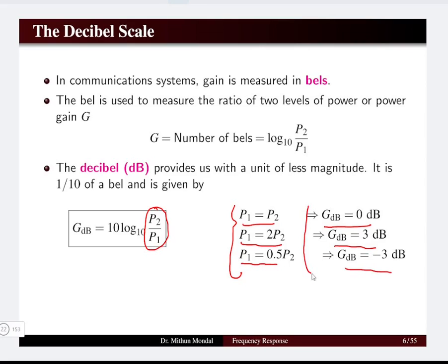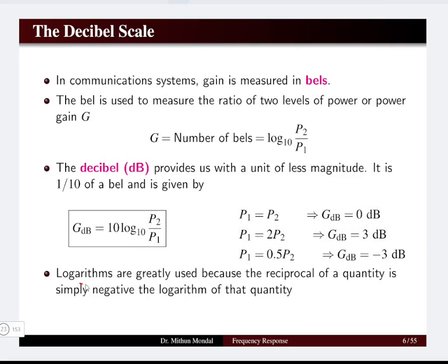So these values will be important to understand why we have gone to the decibel scale and why we have taken the logarithmic as the important part in determining the frequency response. The logarithmics are greatly used because when we obtain the reciprocal of a quantity, we can see that here we have taken twice and here we have taken the half, which is the reciprocal, we are simply getting the negative logarithmic of that quantity.